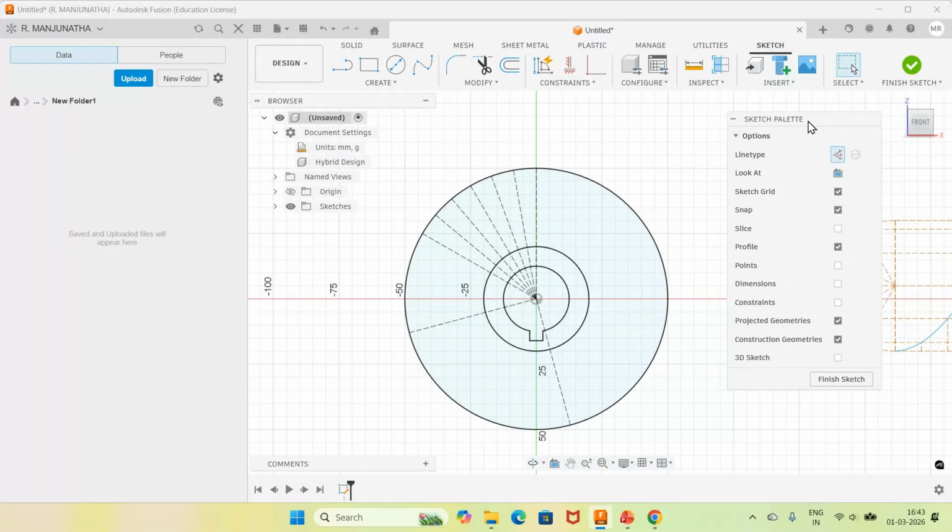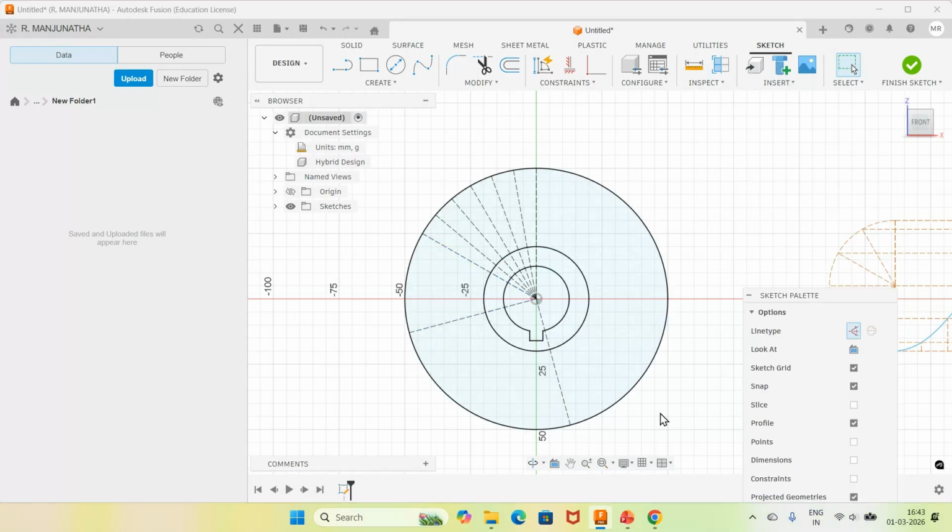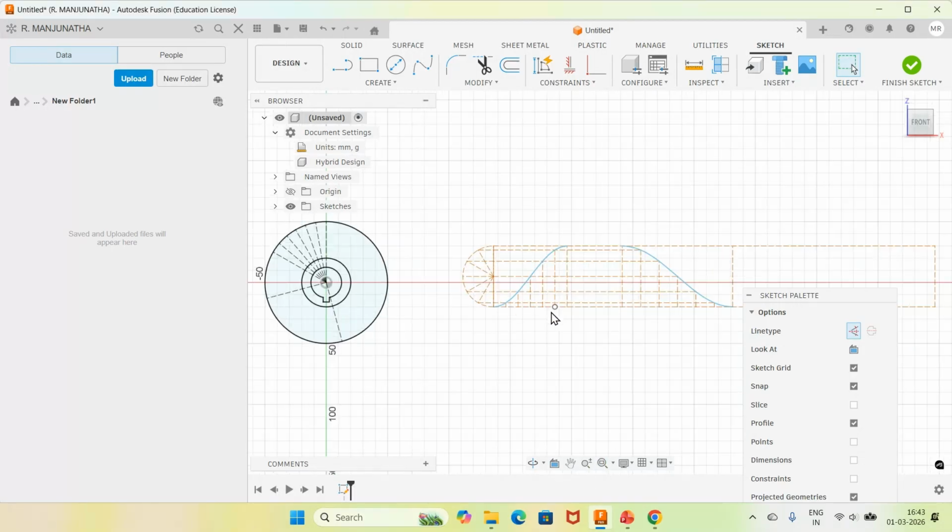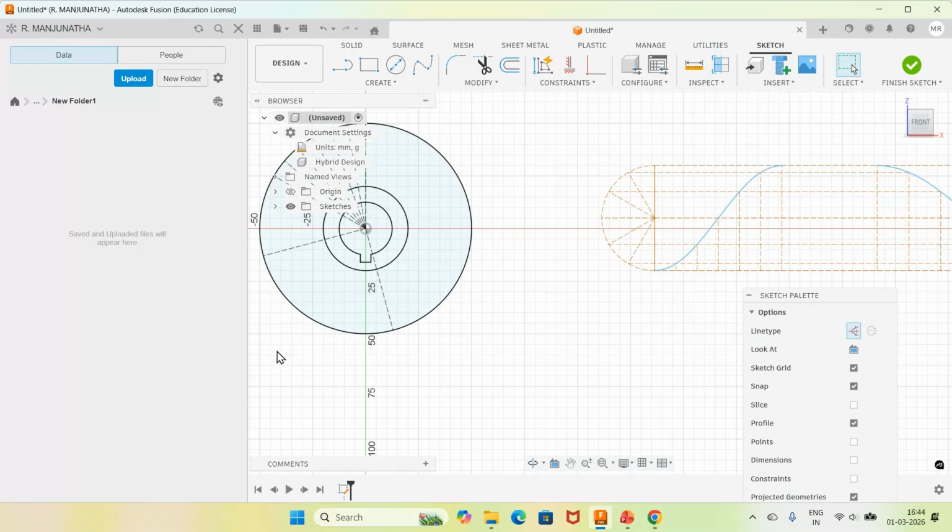Then from here again 45 degree, it is the dwell period. So that means here when you go for theta, you can see this outward has been done. Then from here to here it is 45 degree. There is no variation in the displacement, it remains at the same point, at the same radius or the same lift of 50 mm. And again it should come back. So this has to be divided into again 6 segments. So I want to construct by this.